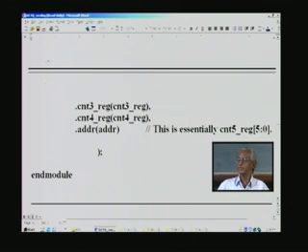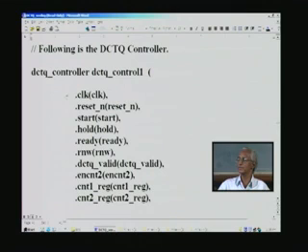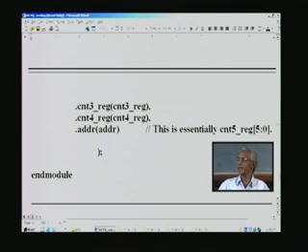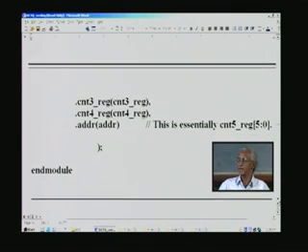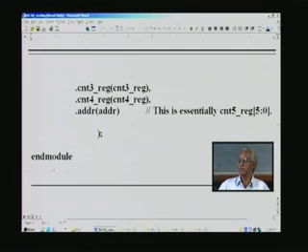Now you would have noticed an interesting feature which I have explained right in the beginning. There is no logic in the top design module. It is merely calling the different modules that you have seen here, everywhere just calling the modules, adder or multiplier as the case may be. And a good design practice, once again to reinforce the statement, is to avoid any logic on this.